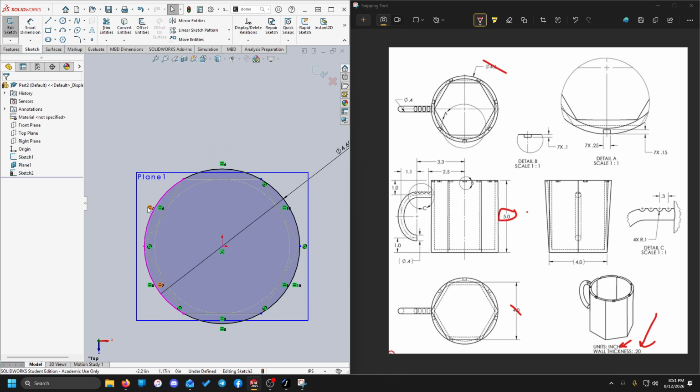So that already gives us these nice and easy equal length relations that connect all of the pieces together, and it gives us co-radials that make it so that they all have the same radius and they're all concentric with each other. So much easier than trying to draw that out by hand.